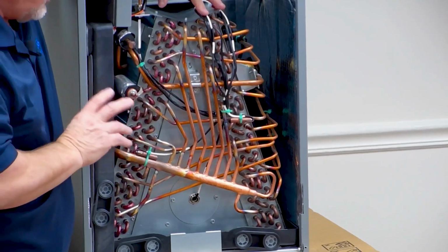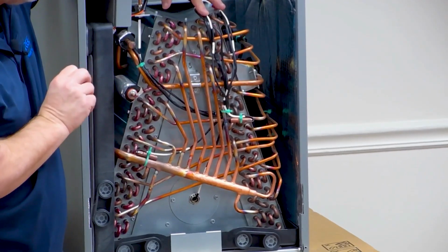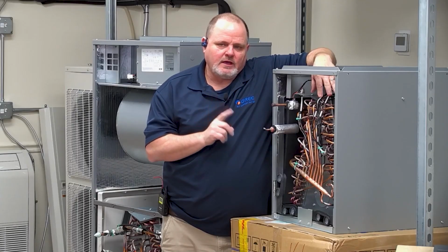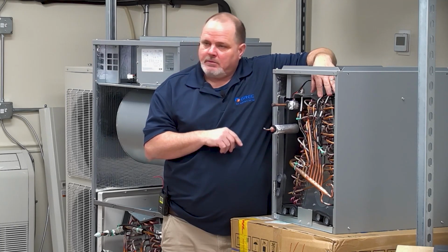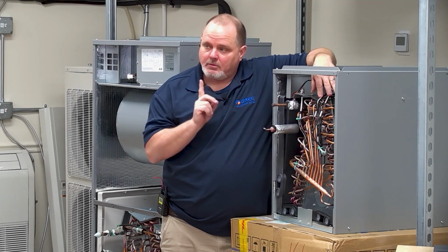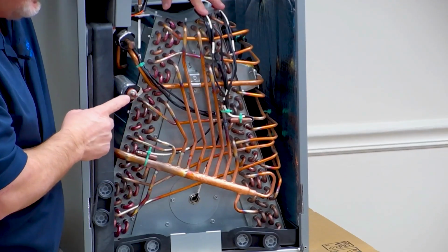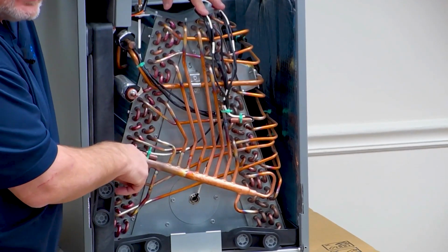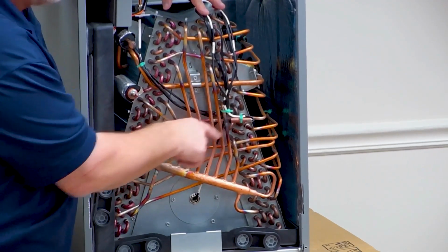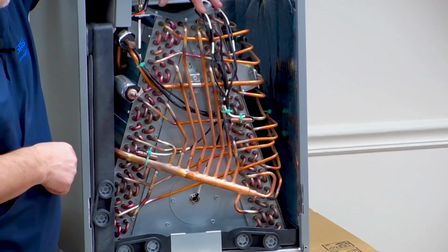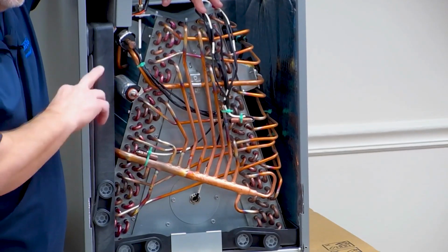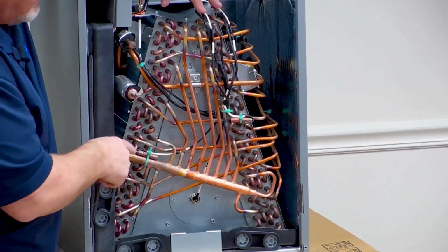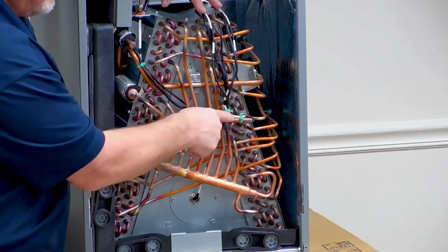The one thing I want to point out, make sure you realize, is that on the service tool they are marked as inlet and outlet pipe temperature sensors. If you're in heating mode, that's backwards, because in the tool it still says inlet and outlet, but remember, you're flow reversed. Now we're flowing hot gas into here, so your outlet temperature sensor becomes your inlet temperature sensor, and your inlet becomes your outlet, because your refrigerant is flowing the other way. You have to keep that in mind in heating mode: inlet and outlet are reversed. In cooling mode, that is your inlet, that's your outlet. In heating mode, that is your outlet, and that is your inlet.